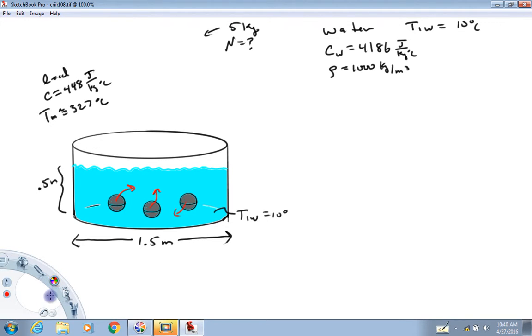Now, the key factor here, though, is that while that occurs, again, go back to the system. If we define our system like this, no energy has gone across that boundary, which means if we add up all the pluses and minuses, as far as the energy transfers are concerned, they should add to 0. So we can actually write an equation that says that. I'll start with this. The heat transfer for the cannonballs, or I'll say the lead, plus the heat transfer for the water should sum to 0, again, because of my discussion about no energy transfer across that green boundary.